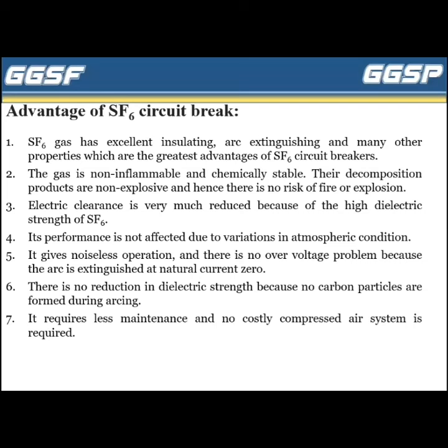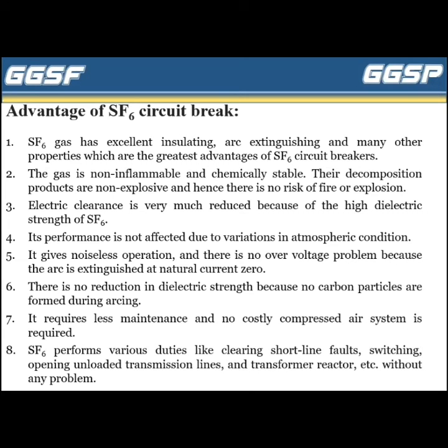Sixth, there is no reduction in dielectric strength because no carbon particles are formed during arcing. Seventh, it requires less maintenance and no costly compressed air system is required. Eighth, SF6 performs various duties like clearing short line faults, switching, opening unloaded transmission lines, and transformer reactor, etc. without any problem.